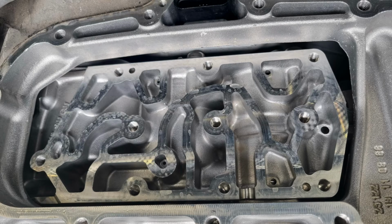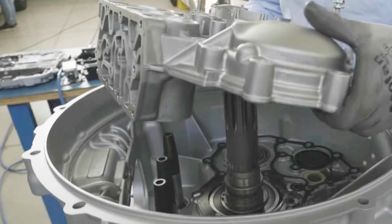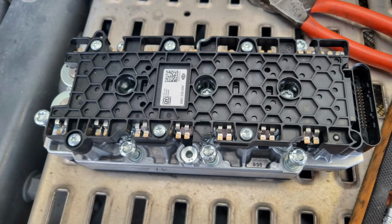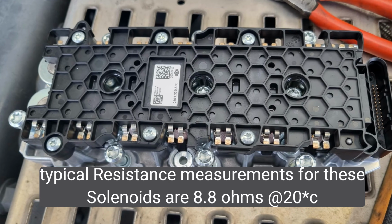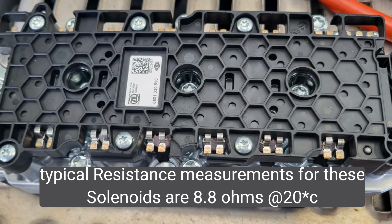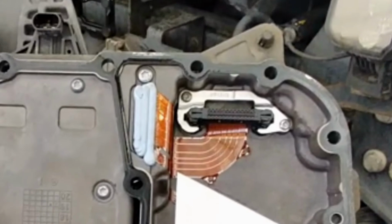Next we have the valve module. This has the task of supplying air to the pistons that move the shift rails. It provides pneumatic control of the clutch actuator and regulates the air pressure to it. It also measures the air pressure. It also houses all the solenoids which work the splitter group, gears, low range and high range, transmission brake, clutch close and clutch open.